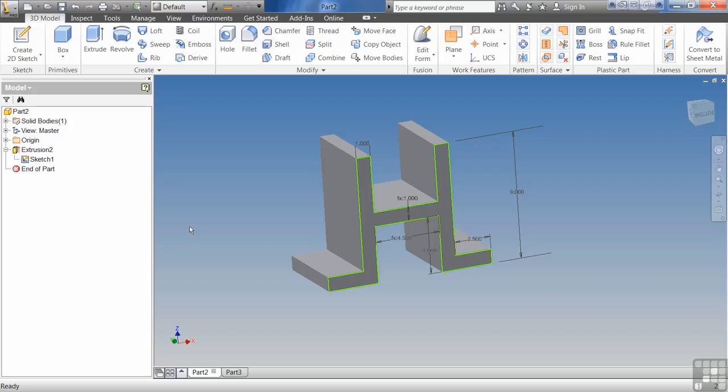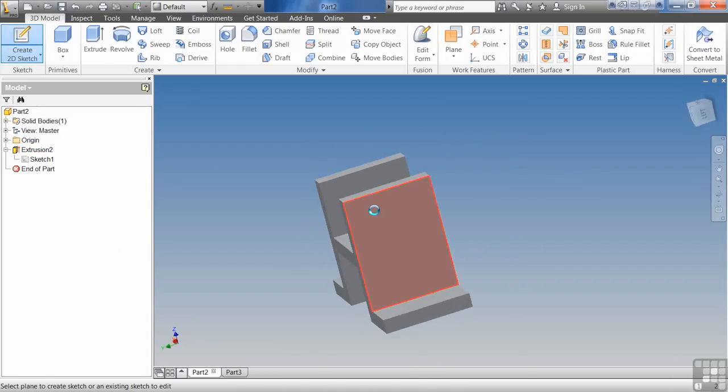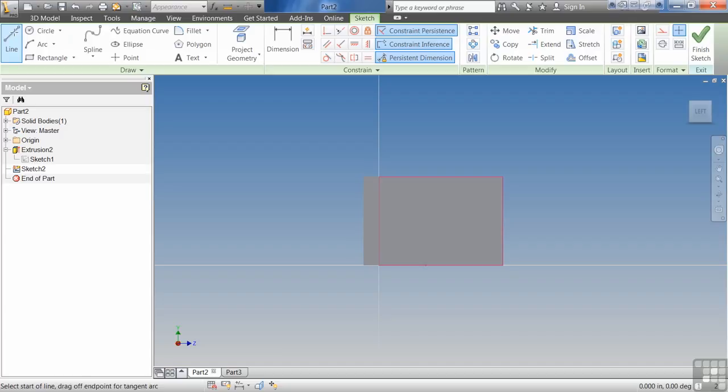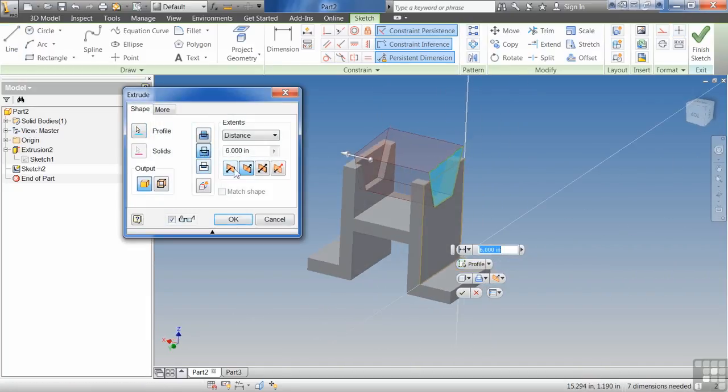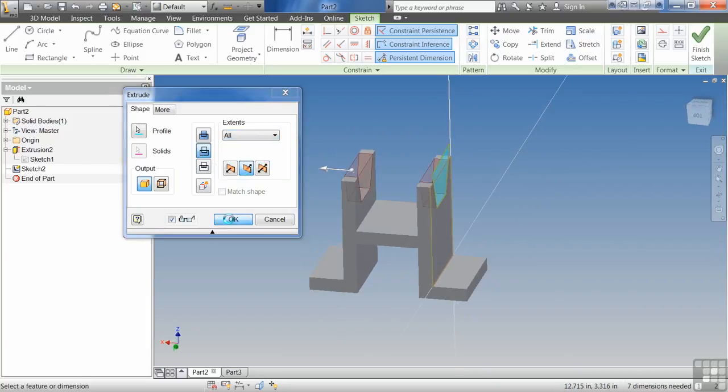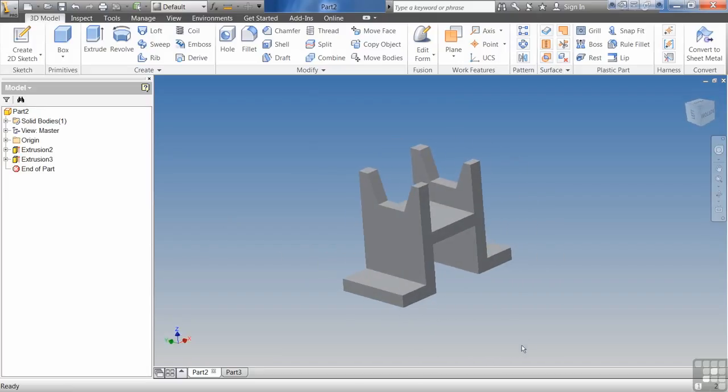Typically, whenever you're creating sketches, you're doing it for a base feature to start with. So that we get a base feature. And then we may come over here and do a secondary feature on the side of this. And I can do a cut. I could say through all. My initial sketch was the H, and then the secondary sketch gave me this cut through here.